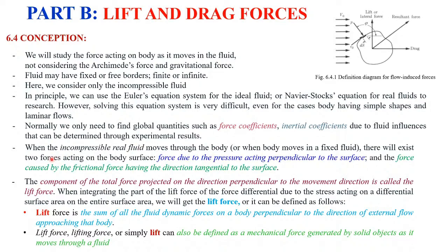When the incompressible real fluid moves past the body, or when the body moves in the fixed fluid, it's the same. There will exist two forces acting on the body surface. This is very important. You remember the force due to the pressure acts perpendicular to the surface, that means the normal component.